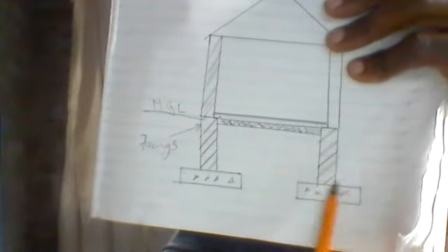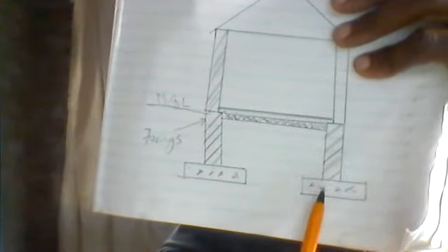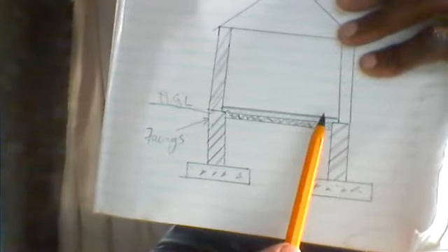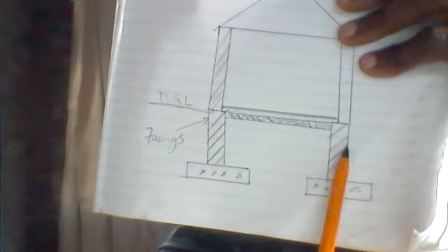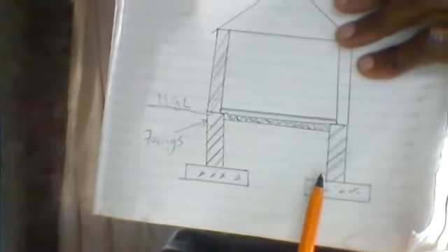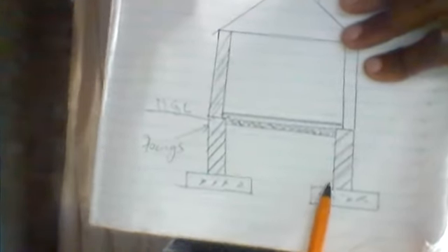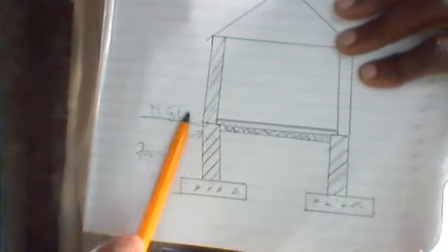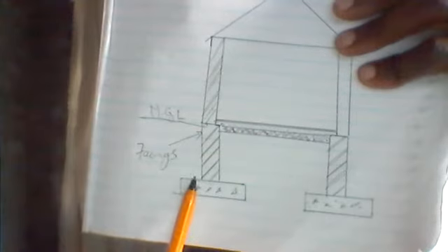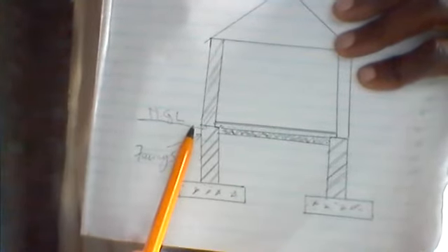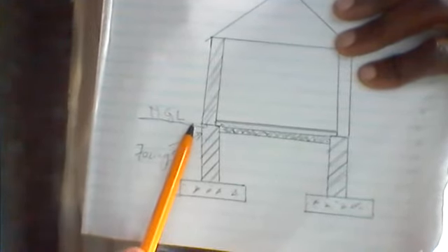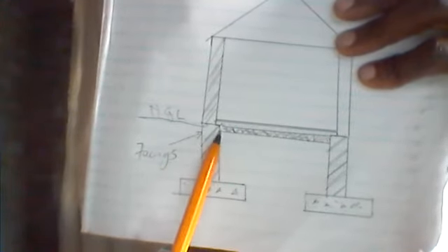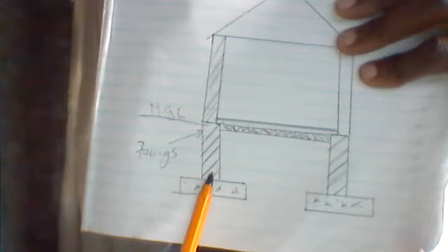We are on foundation, we are here. On top of the concrete footings to the natural ground level, there is a 330 wall. If you can check, the 330 wall starts from here to here, which is our natural ground level, on top of the footings to the underside of natural ground level.